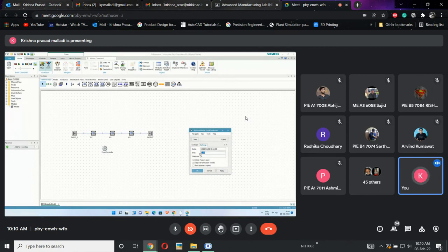If I want to give 5 minutes or 10 minutes, and I directly give 10 and click apply, what will happen? It will be considered as seconds. Now I don't want that. So for that 10, if I press the semicolon, then it will be considered as 10 minutes. Okay, same with 30. If I want to run the simulation for 30 minutes, 30, apply, 30 minutes. Same with hours.